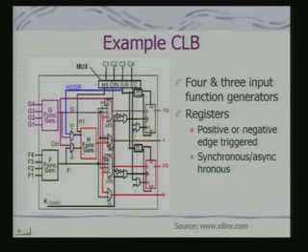These are all multiplexers, and this input is basically your control input. That means, using these inputs, you can configure the system to synthesize different functions. If you look at this path, it tells you whether this H1 is to be computed or not. The other information coming out, your control inputs for the multiplexers and others, can also be provided through these inputs.